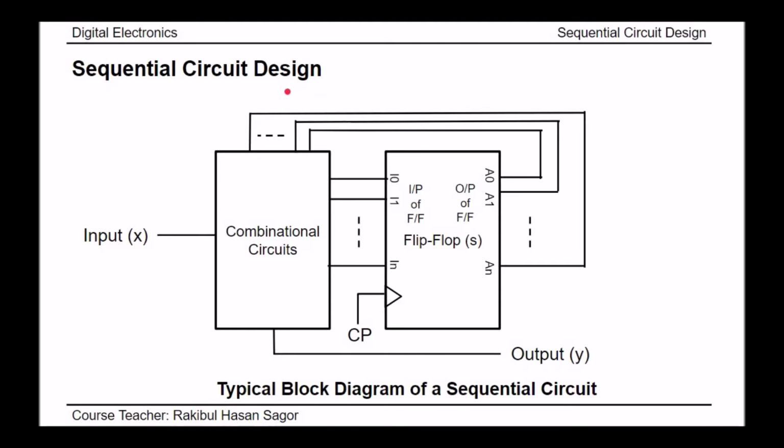Here in this slide, we can see the typical block diagram of a sequential circuit. In order to design the sequential circuit, we need to know the block diagrams so that the designing procedures become a bit easier. First of all, there will be a set of flip-flops, and these flip-flops will take input from the combinational logic circuits. We may have n number of inputs and n number of outputs. These are the inputs of flip-flops.